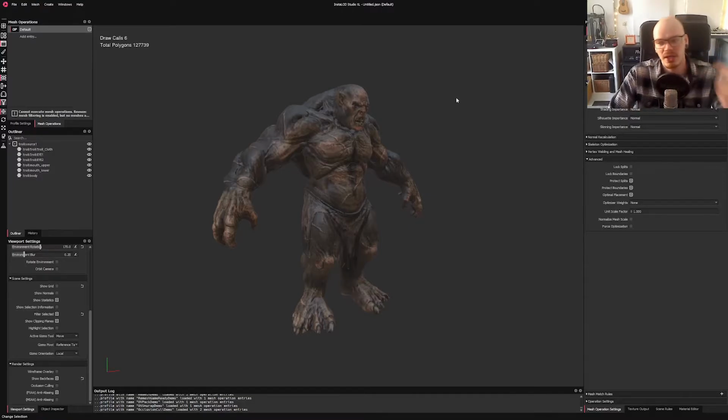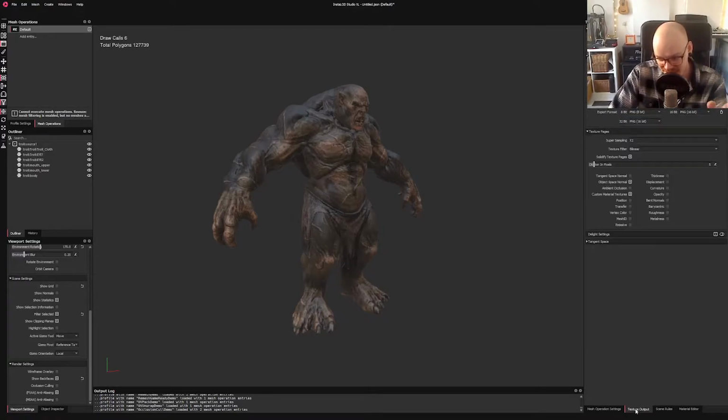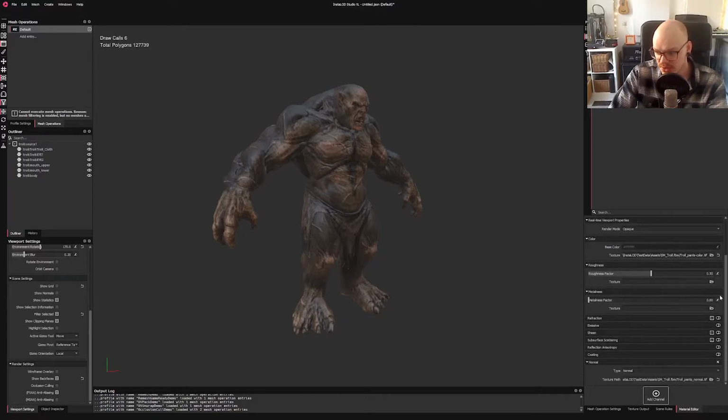Now what we're going to do is, in our case, we're going to use the remesh. There are different ways of combining the textures. For example, material merging, which is what I mentioned earlier. But in my case, I'm going to use the remesher, which automatically utilizes the baker. The remesher is going to do a full reconstruction of the scene. It's going to generate new UVs, and it's going to bake the textures together into a new texture. And this is really useful because at this point, we've got 3 input materials. And we've got, I think, 4 different textures, or actually even more.